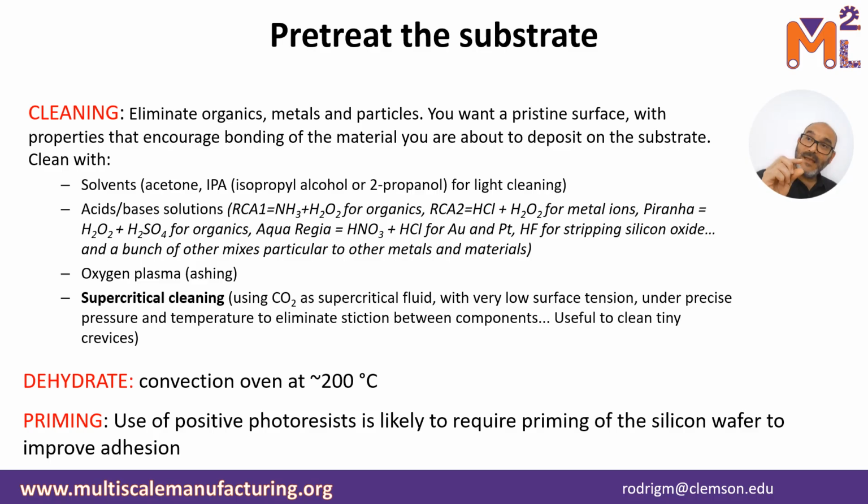And also the difference in the coefficient of thermal expansion between the substrate and the material that will get developed during the heat treatment, right? So the SU8 will slowly morph into carbon. Those intermediate materials will have different coefficients of thermal expansion that might also impact the substrate itself. So always consider those differences, right? And try to have coefficients of thermal expansion as similar as possible in order to prevent drastic deformation of your structures.